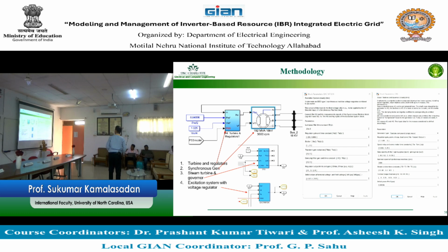Inside the generator, if you look at it, well, this is the governor. But if you look in the generator, there are inertia constants. Have you seen the inertia constant in the generator parameter box, like H? Let's keep reducing that number. That also will do it. And then let's see what happens. And then you try to build in IBR, and see what happens. Then you start working on some controls on IBR.